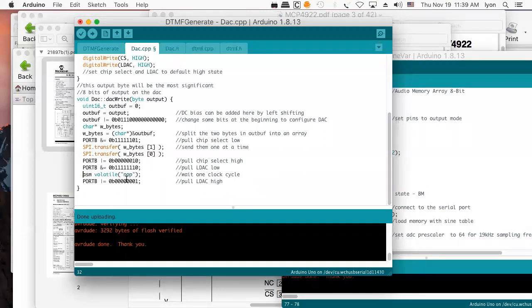So you want to load the DAC, and you want to give it a little time to load the next number. That's what this ASM assembler is for. This NOP is actually the symbolic assembler machine instruction for no operation. And NOPs on a microchip, I'm not quite sure how many cycles they take, but they're pretty fast.